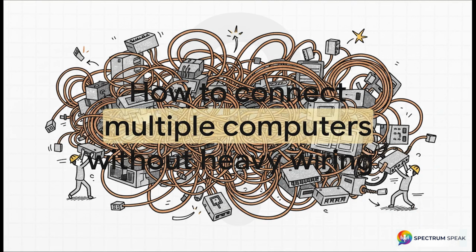To really get why CAN is such a game changer, we have to look at the massive headache it was actually built to solve. Up until the 1980s, cars really had very few electronic units. But as tech evolved, engineers used point-to-point wiring. Think about that for a second. If ECU A needed to send a signal to ECU B, you literally ran a physical copper wire between them. Need to send 3 different signals? Yep, you're running 3 separate wires. Scale that up to dozens of computers, and suddenly your wiring harnesses are impossibly thick, insanely heavy, and just an absolute nightmare to manufacture or troubleshoot.